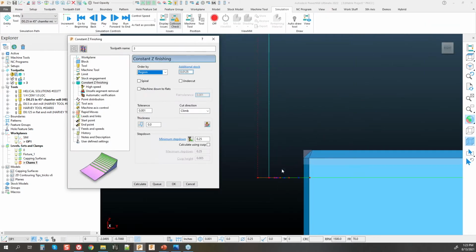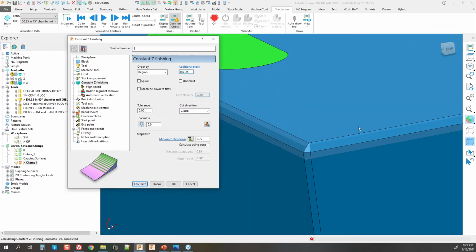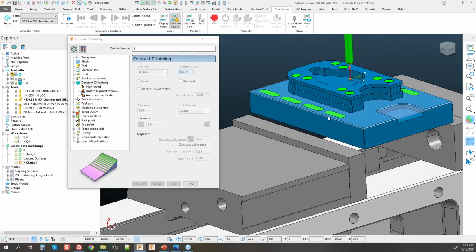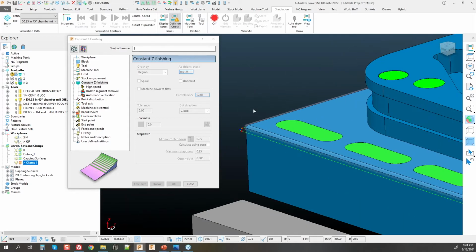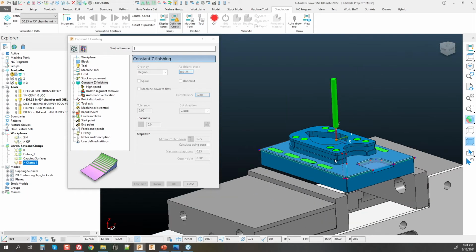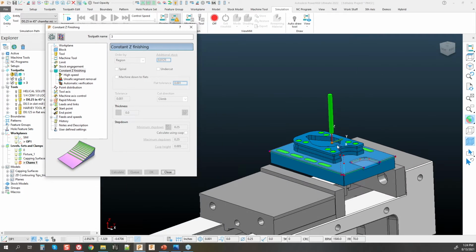Now, the reason why I'm showing this is because these are kind of toolpaths that we can do automation to as well. So we can apply these techniques to macros where we utilize selected surfaces, whether that's either in sets or levels or even by color within a model. If you select to have features colored within your model, we can actually apply a block to that region, an extent to the block automatically, and calculate a constant Z toolpath and chamfer all of your parts.